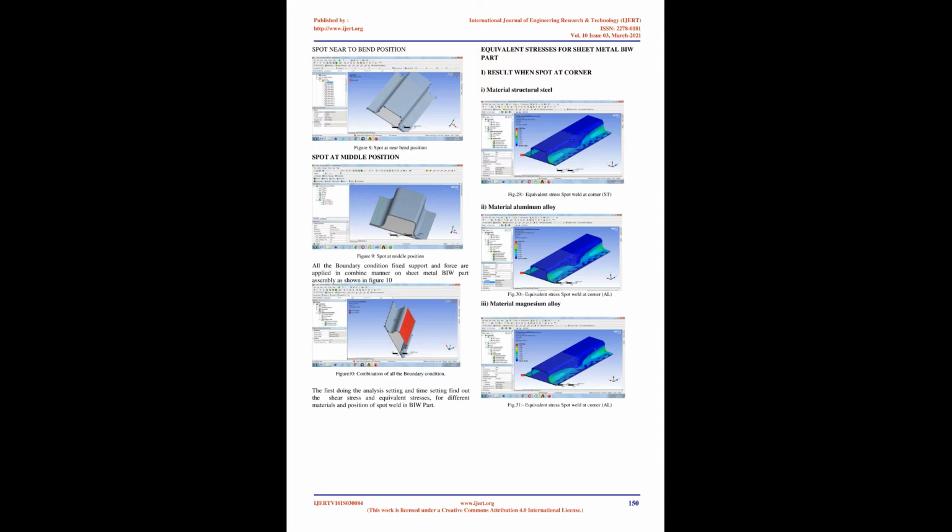Introduction. Resistance welding is the most commonly used method for joining steel sheets. No filler metal is needed, and the heat required for the weld pool is created by means of resistance when a high welding current is directed through the welded workpieces. An electroconductive contact surface is created between the workpieces by pressing them together. Contact is made using the shape of either the welded surfaces of the workpieces or the shape of the electrodes. Water-cooled electrodes made of alloyed copper are used in resistance welding.